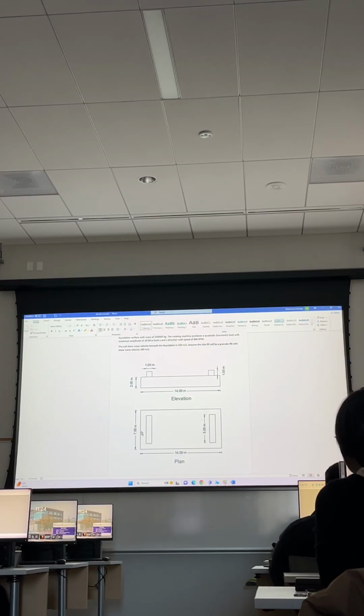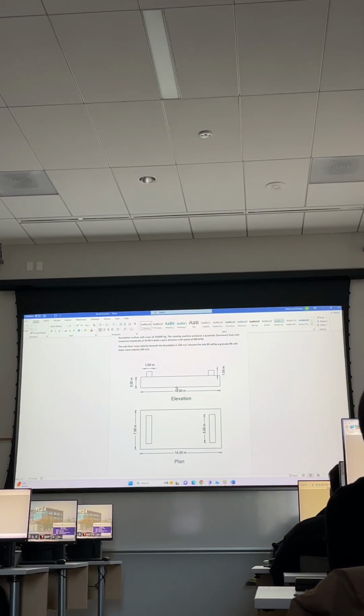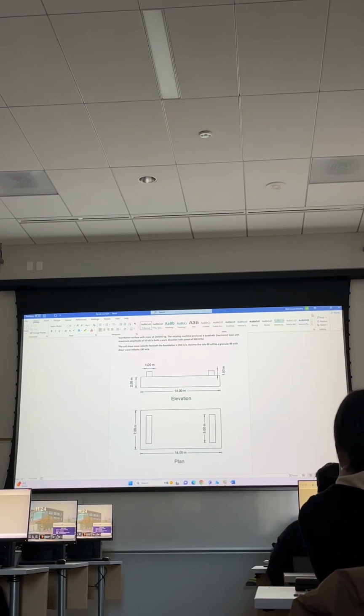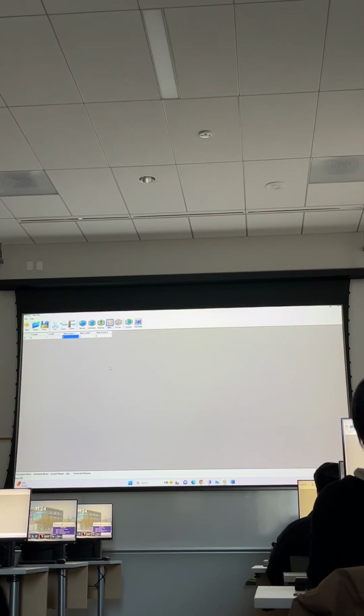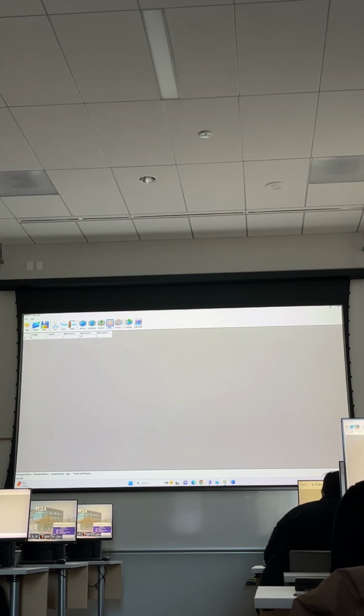This is the dimension, and for the center of this foundation, you will find the center is 7 meters from here in X direction, 3.5 in Y direction, and for Z direction it is 0 because it's the lower part of the foundation. Okay? So here, base center X will be 7, base center Y will be 3.5, and base center Z it's 0. Okay?